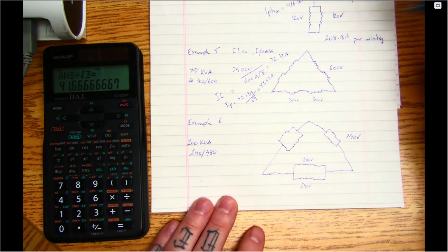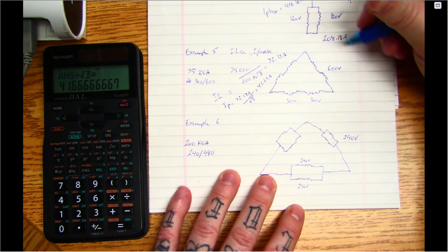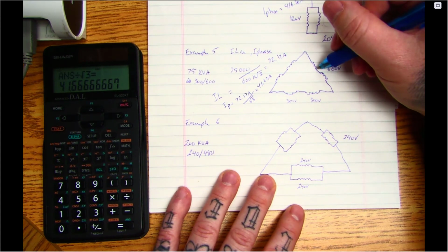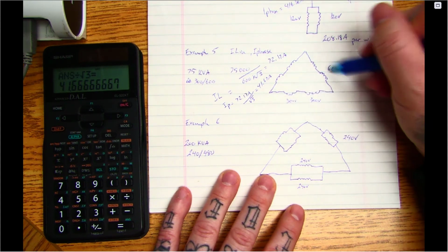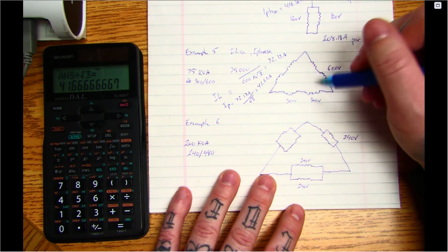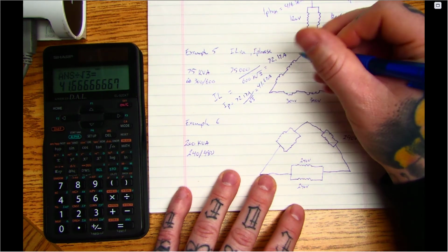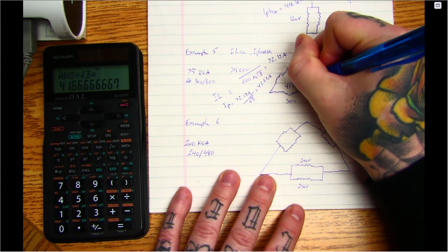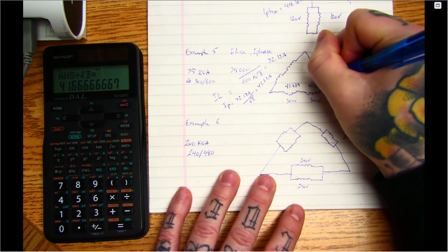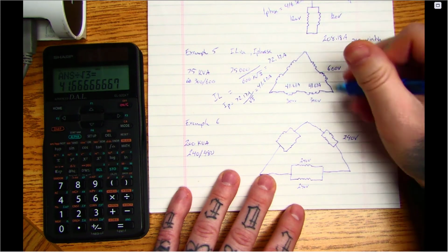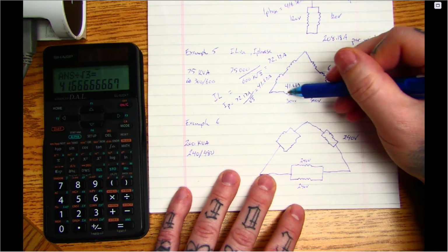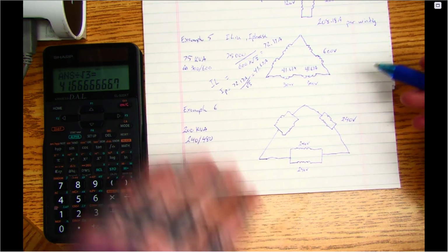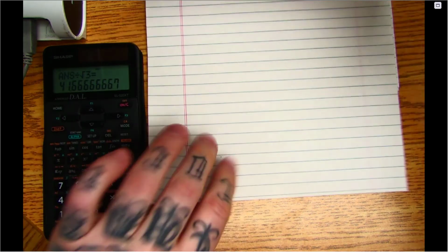41.67 amps. So on a phase level, I'm in series here, so each one would see 300 volts if I have a 600 volt phase, because they're in series, and the current running through each one of these would be my phase current, which would be 41.67 amps. Again, because they're hooked in series. So my I phase is this value, and that's what's going to go through both those windings.